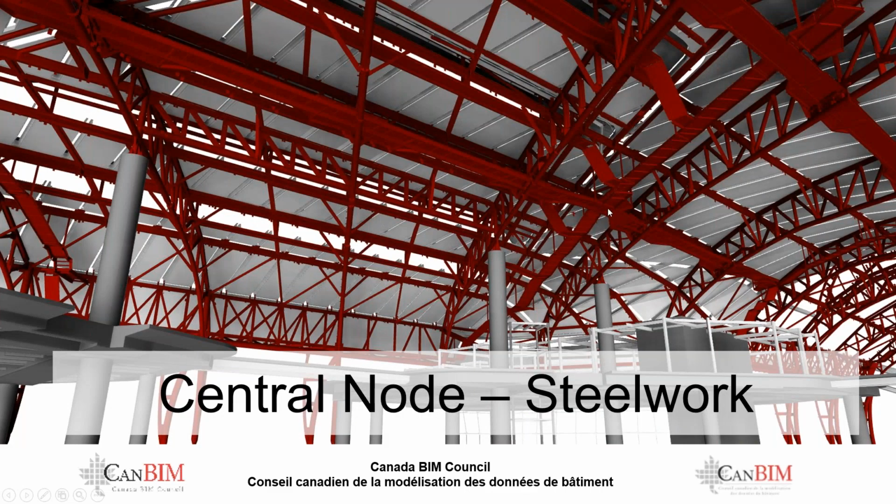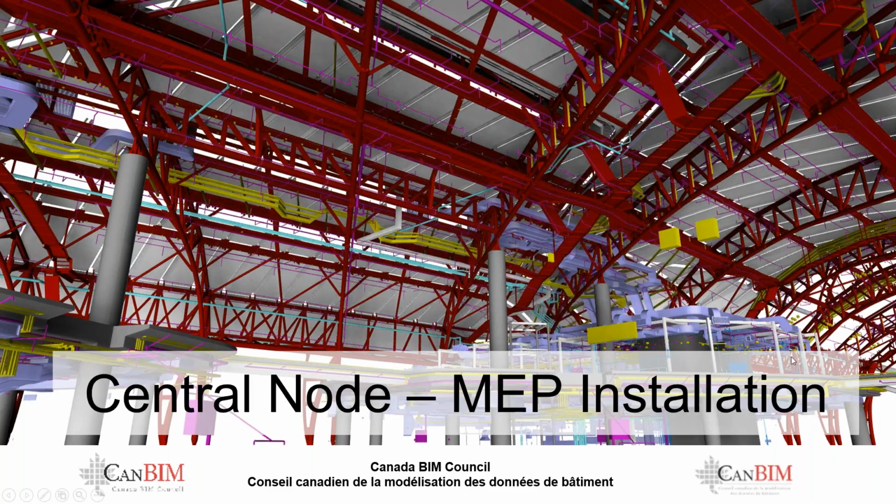But when you start to look at this from underneath, just getting the cladding system onto the building was one challenge, but to actually coordinate all the building services in the space and then to coordinate the ceiling in the space was also an exercise. So the contractor elected to do all of that in 3D using BIM processes. All of the mechanical systems were modeled by the mechanical contractor. So the lessons that we learned on the Cathay cargo terminal was to actually get the mechanical contractors involved in the modeling process, and they would model where they wanted the ductwork, where they wanted the pipe work, where they wanted the cable trays. And they would work with the steel fabricator to make sure that it was all coordinated.